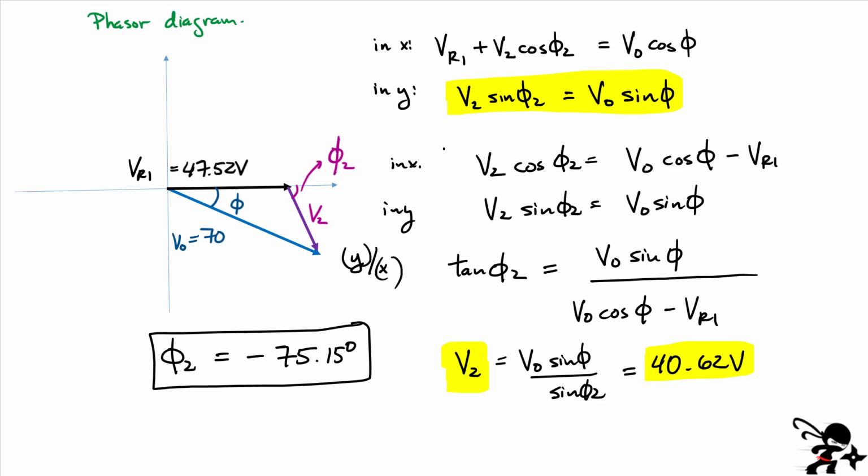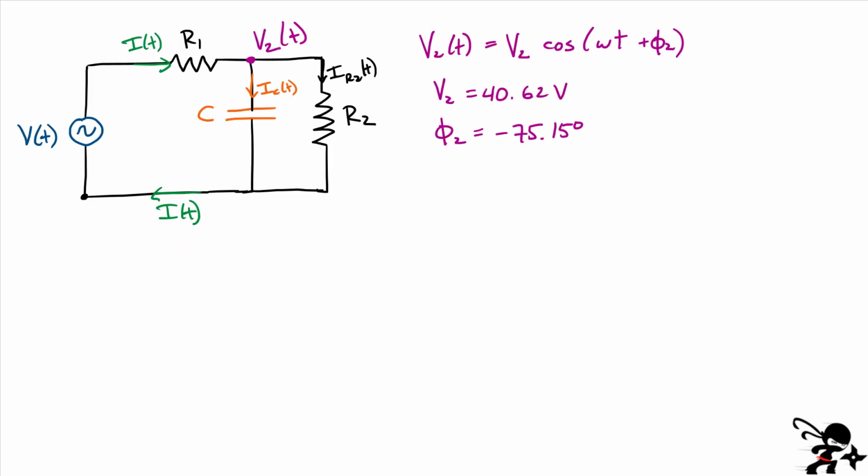Okay, so now we have the voltage at that point in the circuit. All we have to do now is find those last values of the currents through each branch, through the capacitor and through the resistor R2, and then find if there's any phase between the currents in those branches. So we just have to look at how we calculate the current through the capacitor and the current in the branch with the resistance R2. Again, R2 was 100, capacitance was 100 microfarad.